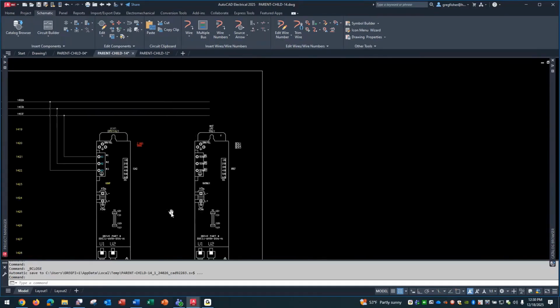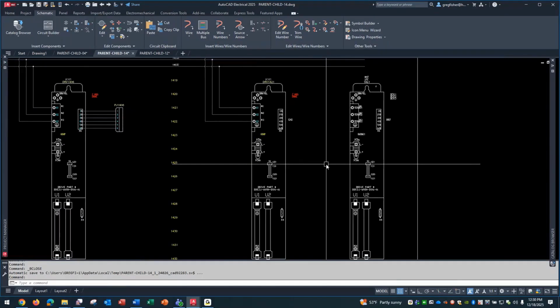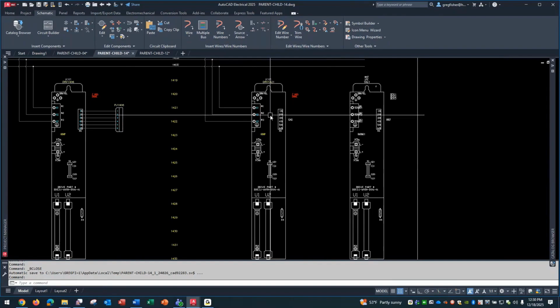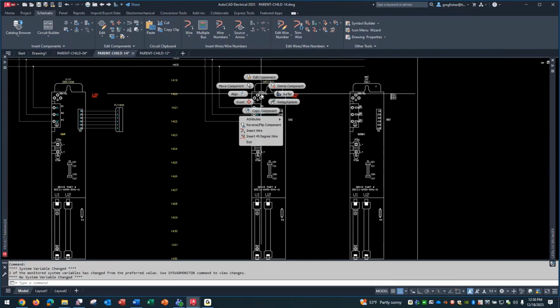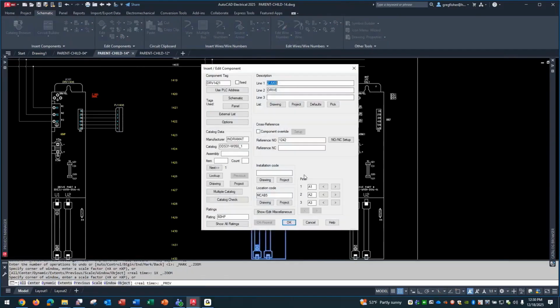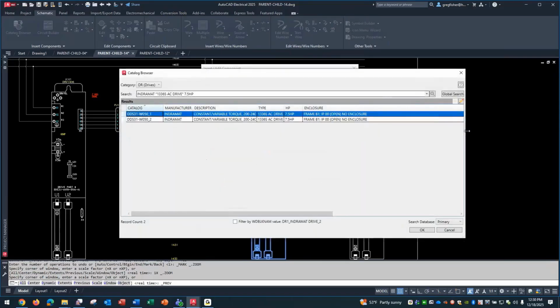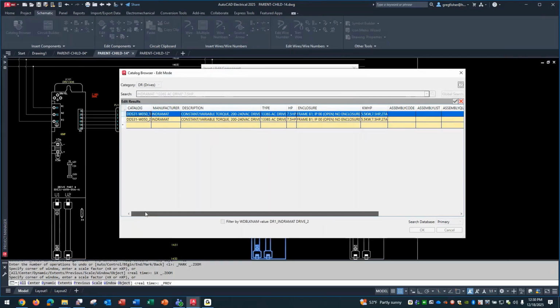And you're not done at that point. A lot of it is about the catalog. Like I just showed you with the relay, to really make it intelligent and not just have two symbols cross-referencing each other. If I go back to edit here, when I added this catalog number, once again, coil pins, think of this as parent pins or parent terminal numbers.